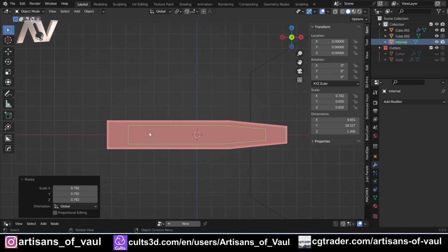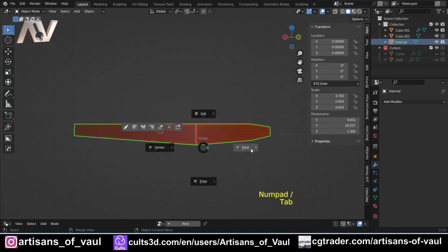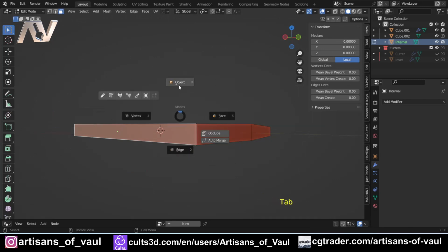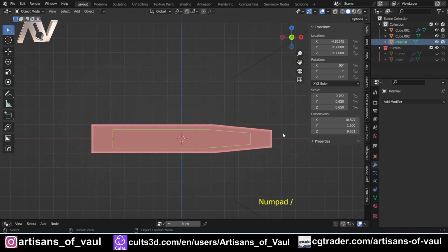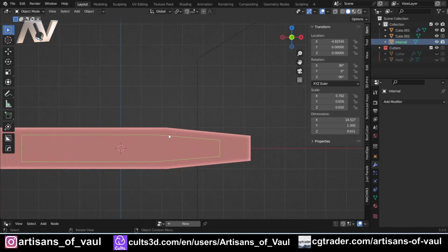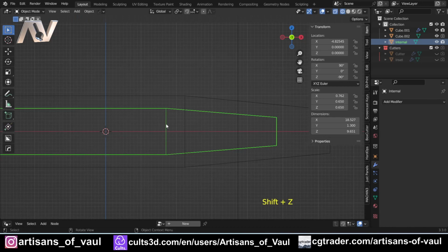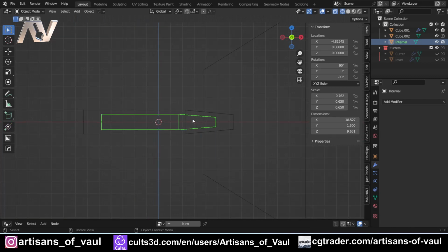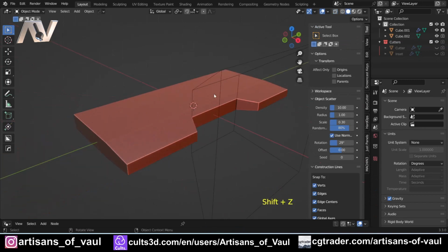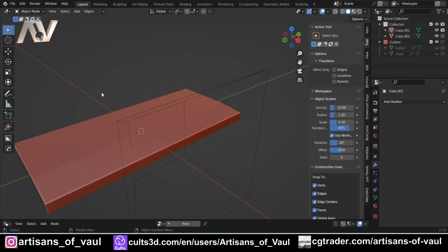Also, if you, for some reason, let's just isolate this and let's go into face mode, select that, Shift and S, and then put the origin to that face. Now if I scale it, you'll notice it's scaling towards that origin. So it's very origin controlled, which actually isn't too bad in this instance. It's actually giving a slightly better result, but it causes problems. I mean, you can do things with this which is quite nice. So for example, you could put your origin on this line to the loop cut when it was here, which means you've got more control and you're going to get less of those problems, but either way it's not great. So actually I'm going to delete that internal object and we're going to have a look at a better way of doing this. So let's just quickly undo this boolean and we'll start afresh.